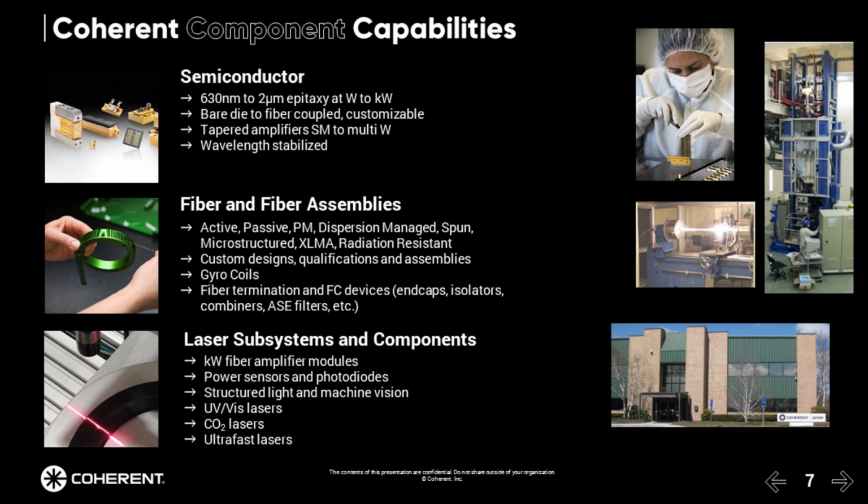We also have an interesting technology called tapered amplifiers. These are semiconductor waveguides that flare from a single mode input to a broad stripe on the output, and therefore you're able to get watt level powers out of a very small chip with near diffraction limited beam quality. And this is beginning to find a lot of use cases, for instance, in the fields of quantum research, as well as in LiDAR and a number of imaging and medical applications.